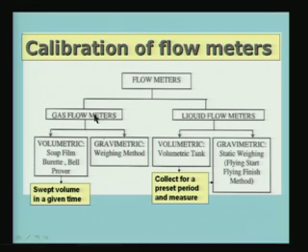The gas flow meters can be either volumetric or gravimetric, that means mass flow or volumetric flow, and liquid flow meters again you can have volumetric or gravimetric. And if you look at the difference between liquid and gas, liquid can be collected easily and it can be measured. That is what I am doing here. I am collecting the liquid for a certain length of time in a tank whose volume I can easily measure.